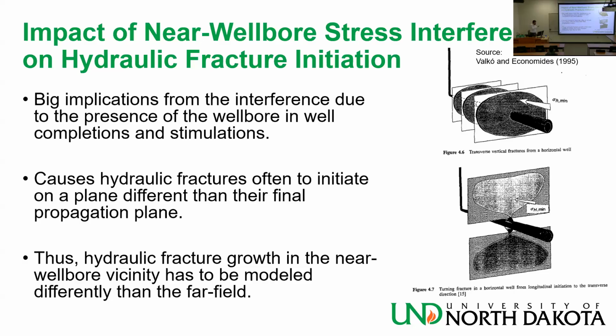So they knew, okay, this fluid with this tracer, we use it to stimulate stage one. This fluid with this different tracer, we use it to stimulate stage two, stage three, etc. And then they did a diagnostic, and they found fluid from stage one into stage three, and fluid from stage two into stage three, and fluid from stage three into stage two and stage one.